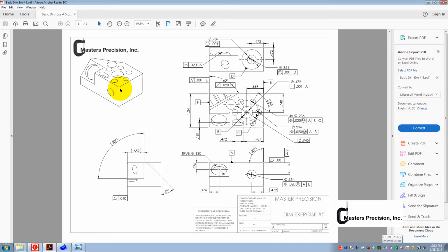So what I'm going to do is not define this plane as datum E, but make an intersection point at this corner and define that point as datum E so that I can do the position note. I designed this so I could show you Cartesian positioning as well as polar. So these holes are going to have polar coordinates, the radial distance and the angle. The radial distance is half the bolt hole circle and the angle is given here. So let's get started.